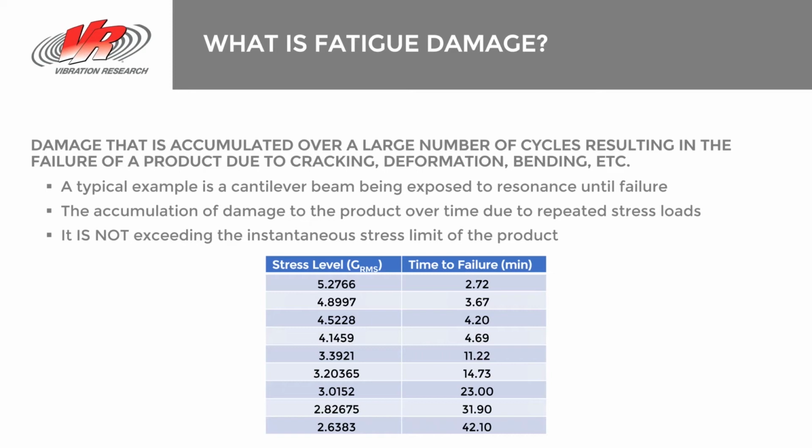So there's all kinds of theories behind this, but in the end, damage is accumulated based on repeated stress load. And if I apply that stress load at different values, it will take longer or shorter periods of time depending on how much I excite, in this example, a cantilever beam.